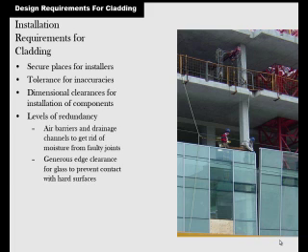Levels of redundancy, the air barriers and the drainage channels, to get rid of moisture from faulty joints. You have to do two or three levels of that to make sure that there's no way that water especially can penetrate your building. You need, like it says, generous edge clearance for your glass so that it won't hit any hard surfaces and crack.